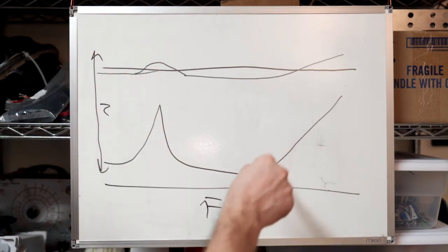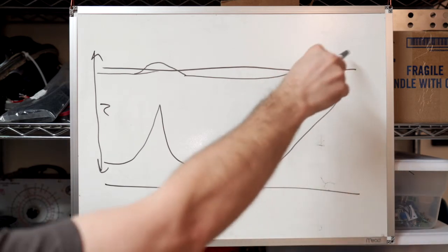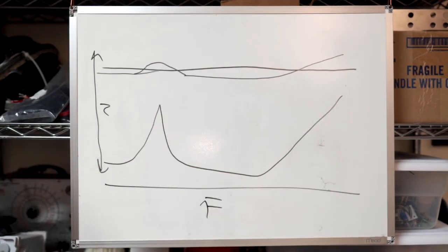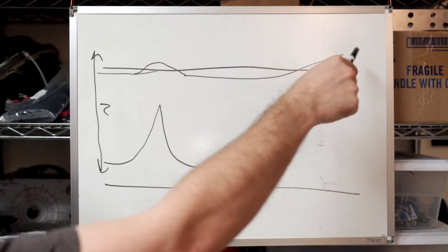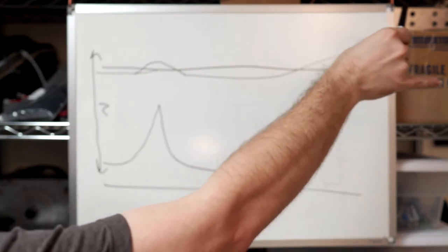Also you'll notice as the speaker becomes inductive up here, we get a little bit of a rise. Let's say this is a high frequency driver that has a little bit of an inductive impedance rise at the high frequencies. Well, you get a little bit of a boost at your high frequencies.